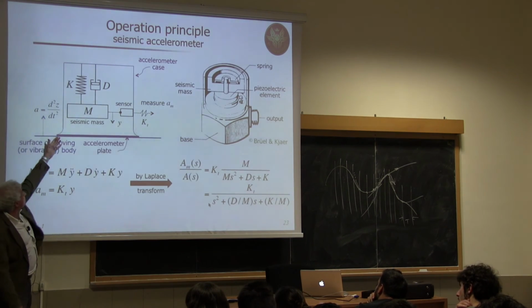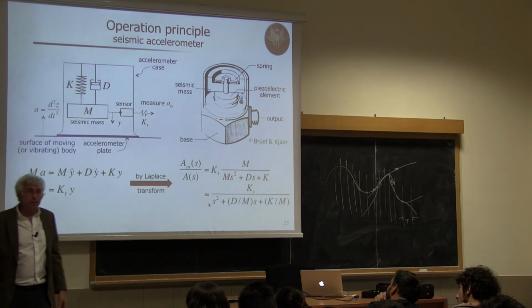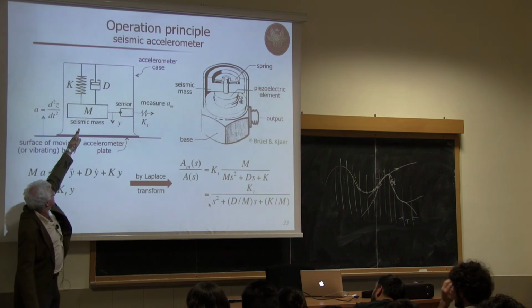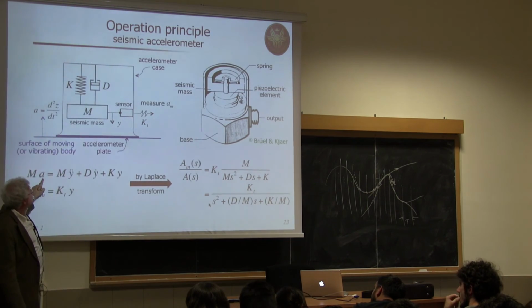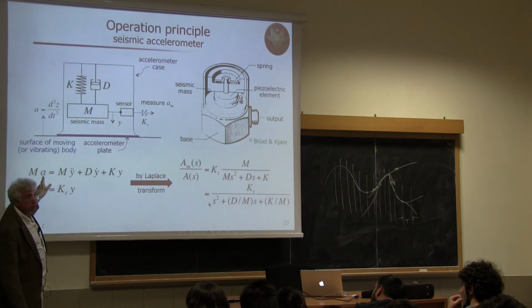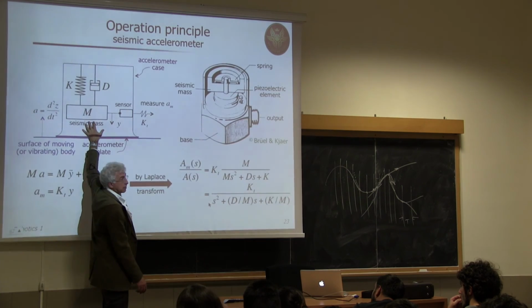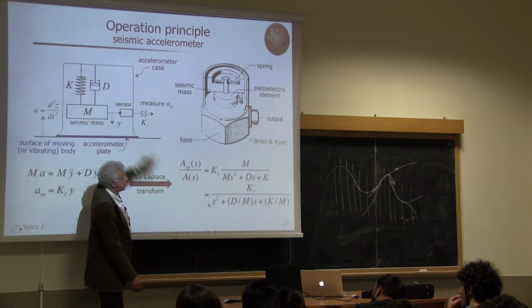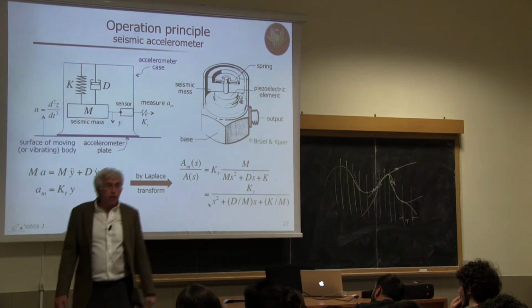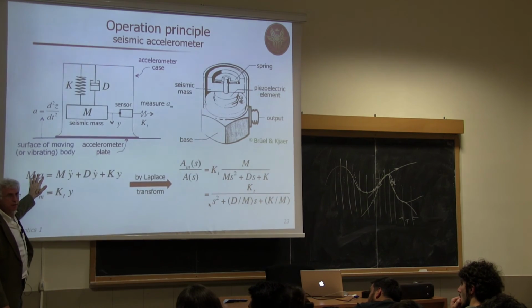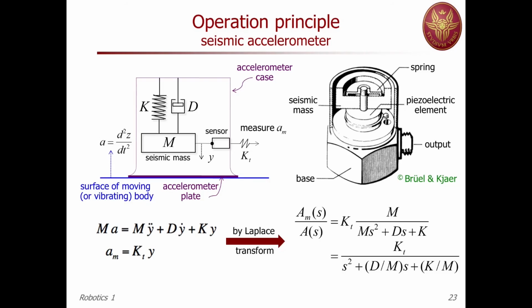Well, we should write some balance of inertial forces for this device. So when I have an acceleration in this direction, this mass undergoes this type of acceleration, which is the one that we want to measure. But in fact, this mass is accelerating in the opposite direction. So I will see a y double dot change. Okay? So the equation is, this is the forcing term which contains m, which is known, but a, which is unknown. And this is what I can measure.